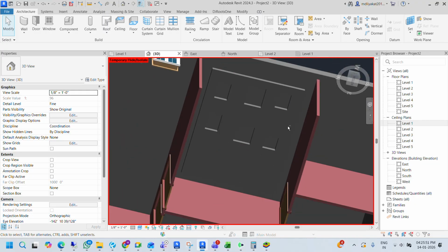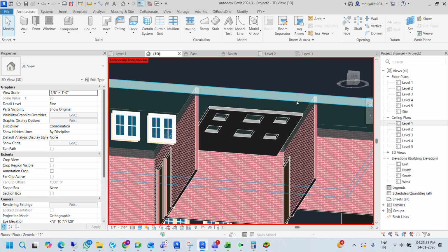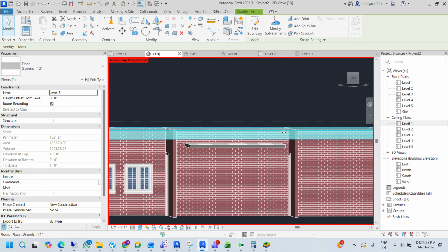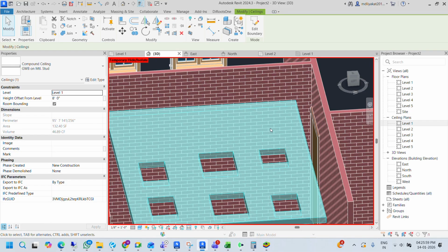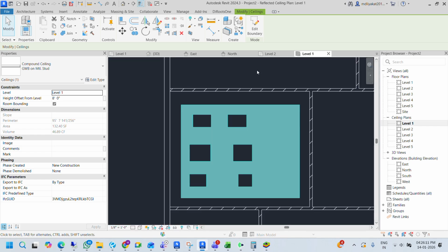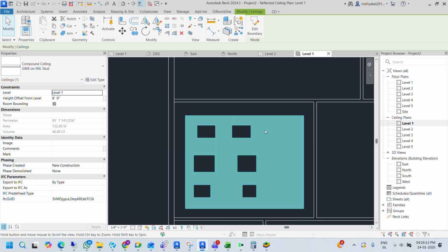The outside surface will be your main ceiling. Hiding this. Your outside surface will be the main ceiling, and whatever blocks you click or edit inside that boundary, it will make holes in it or make a blank space. And one more thing, that is how you can control these ceiling properties as well.